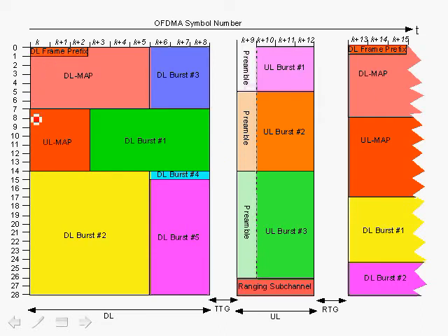The preamble from the base station to all the subscriber stations is implied, and of course throughout the whole symbol here it is not partitioned. During the downlink transmission from the base station to the subscribers, there are pilots that are distributed among the used carriers. Some of those pilots have fixed locations and some have variable locations, but they do not depend on the number of subscriber stations or anything for that matter.